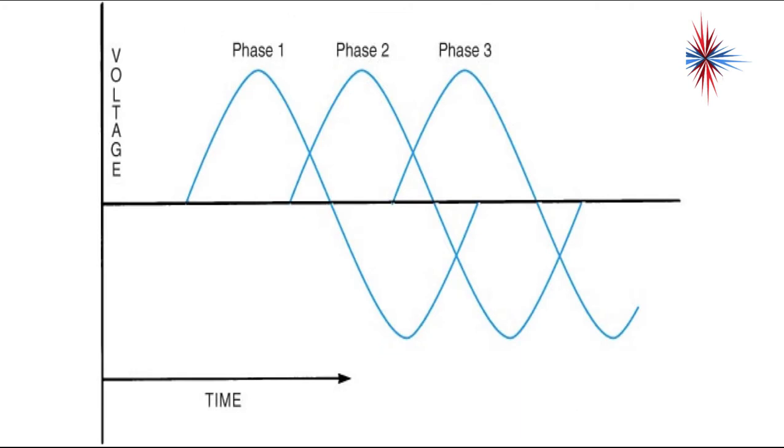This is a three-phase sine wave, okay? Again, we go through cycles. We still have the complete rotation, 360 degrees, but we do it at 3 different phases on 3 different conductors. You'll note if you look at any point in time, there's no more than 1 phase at the 0 point. Okay, and that's something very important to remember as we talk about three-phase power. No more than 1 phase is showing 0 voltage at any point in time.